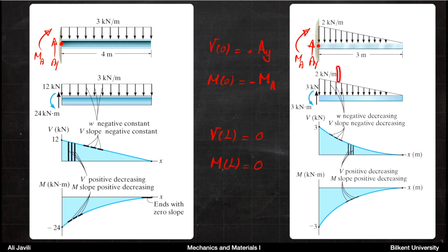And that equivalent force would be applied at the distance 1 meter, telling you that the moment must be also 3 kilonewton meter and counterclockwise, which is the opposite of the direction that we assumed to keep equilibrium.